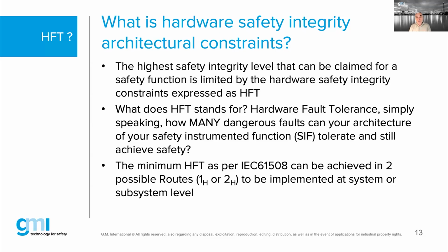If one contact does not work, we want to have this other contact, depending on the architecture, whether it is normally open or normally closed, so it is either in series or in parallel, or a mix of that. We call that, in the terminology of the standard, HFT. And HFT, which you see here on the left-hand side, stands for hardware fault tolerance. You can ask yourself the question: how many dangerous faults can I tolerate and still achieve safety?